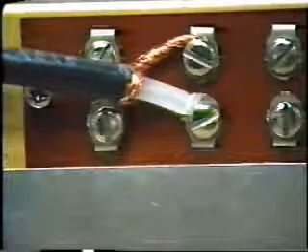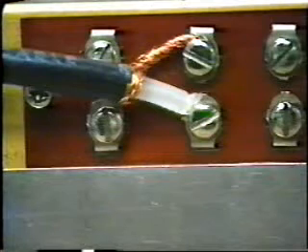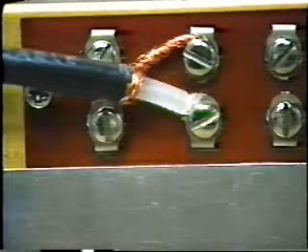The connection of the cable to the LMU is sometimes a problem. If a coaxial connector has been used, make sure the connection between the braid shield and the body of the connector is solid. If the connection is hardwired, check for high impedance paths to ground and burn marks between the center and the shield of the coaxial cable.